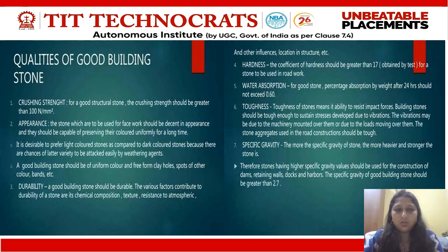These are a few of the qualities of good building stone. The very first one is crushing strength. For a good structural stone, the crushing strength should be greater than 100 Newton per mm square. It should have a good facing appearance. Facing here means the front portion, so that it may impart a good look to my structure. It should be of uniform color and free from any type of clays, holes, spots, or any other bands, etc.